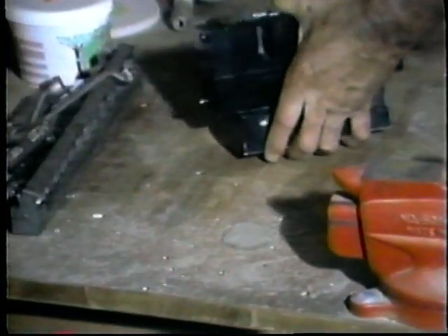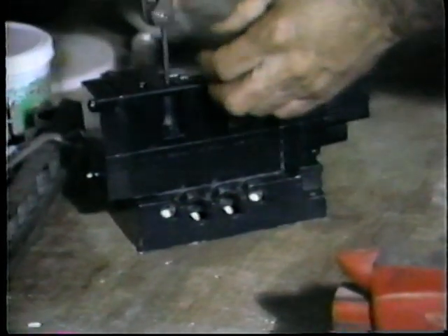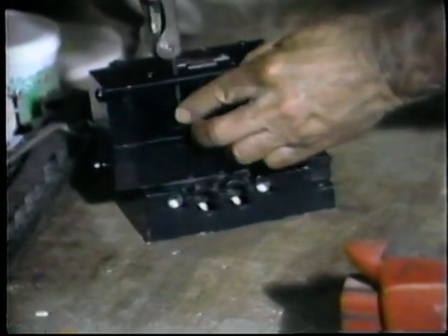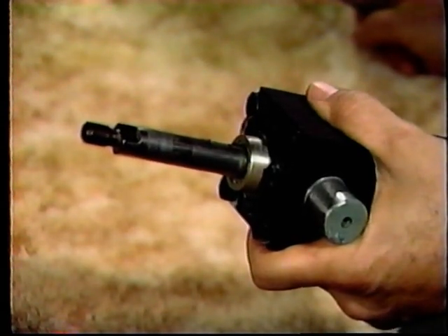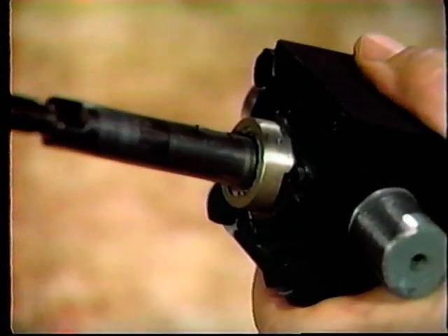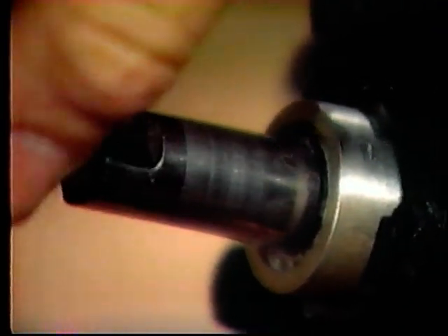The third source of contaminants are those added to the system, that is, ingested. Here's a good example. A mechanic repairing a valve in a dirty environment. Unless he's very careful, it's quite likely that some of the grit will end up inside the valve before he's done. Dirt can also be added to a system through a cylinder. When the cylinder rod wiper wears so the outer sealing edge isn't able to wipe off the fine particles of dirt, they can be drawn into the system as the cylinder is stroked.